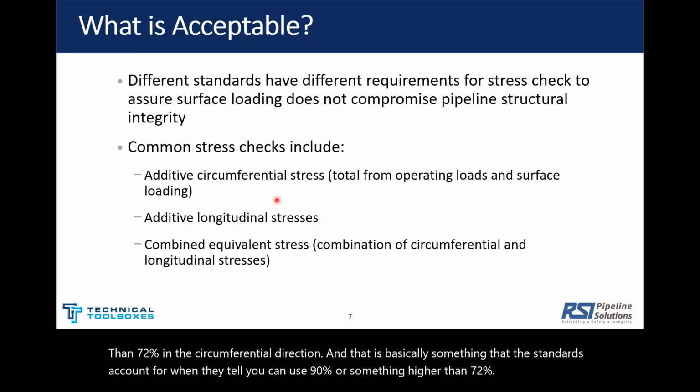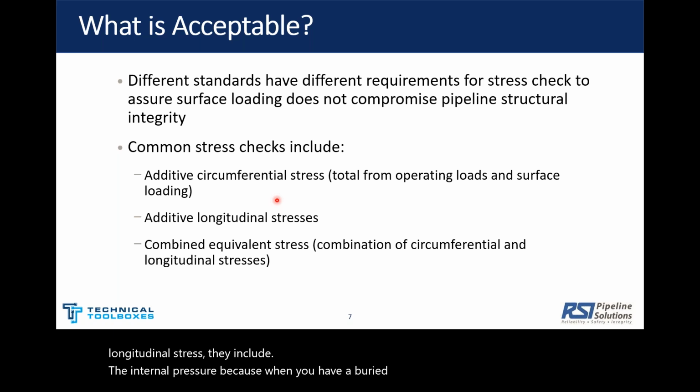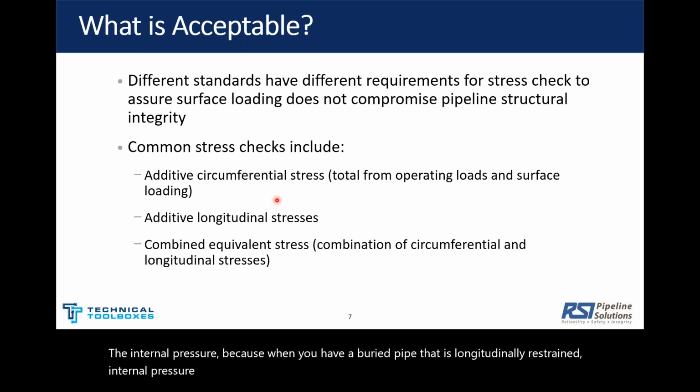So for the additive longitudinal stress, the components that contribute to it include the internal pressure, because when you have a buried pipe that is longitudinally restrained, internal pressure creates some tensile stress in the longitudinal direction.